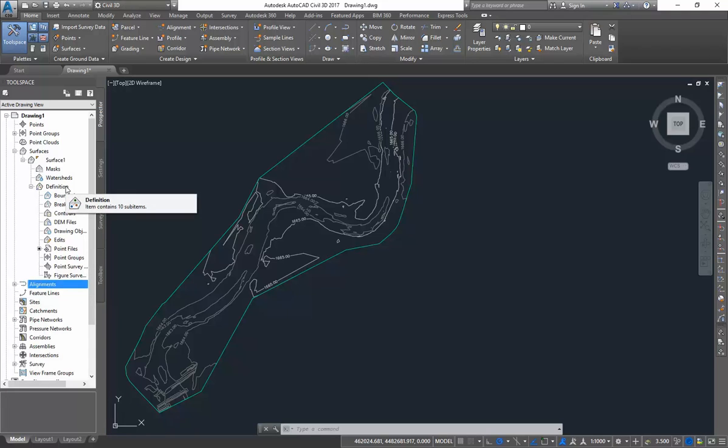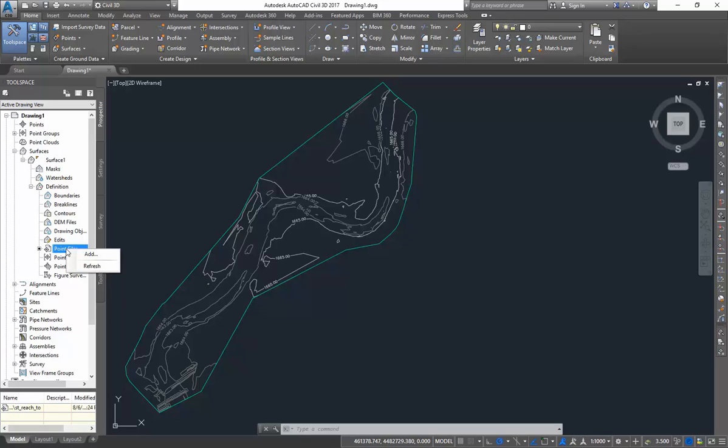So it's all the different information that can be used by Civil 3D to define what the elevation of your surface looks like. For ours, because we went through the process where we used the menus up above and added the point files, you'll see that you have an indication here that point files are there. If you sent your survey crew out, maybe we were showing how it didn't have good surface information in this area, and they got some additional points, you could go through and add those points in here, and it would take all the existing information and also add that additional information.